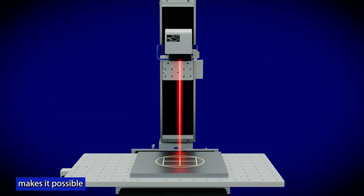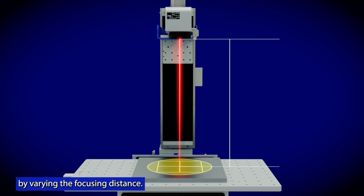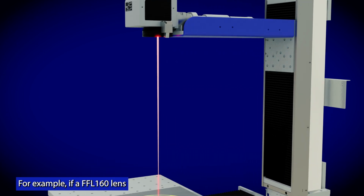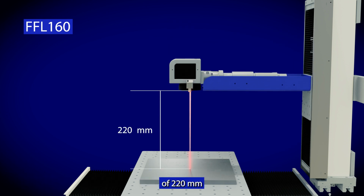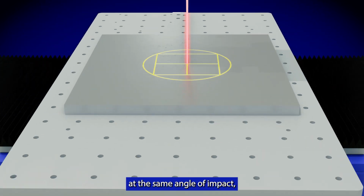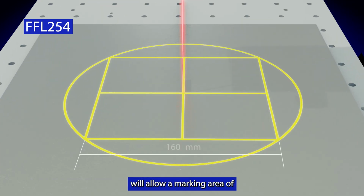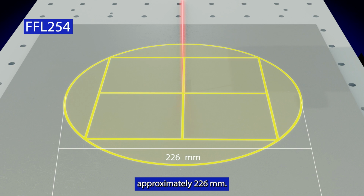The focal lens makes it possible to have different marking areas by varying the focusing distance. The marking area will be greater as the focal distance increases. For example, an f160 lens allows a focal distance of 220 millimeters and will have a marking area of 100 by 100 millimeters, with a circle with a diameter of approximately 141 millimeters at the same angle of impact. A 254 lens at a focal distance of 330 millimeters will allow a marking area of 160 by 160 millimeters, with a circle with a diameter of approximately 226 millimeters.